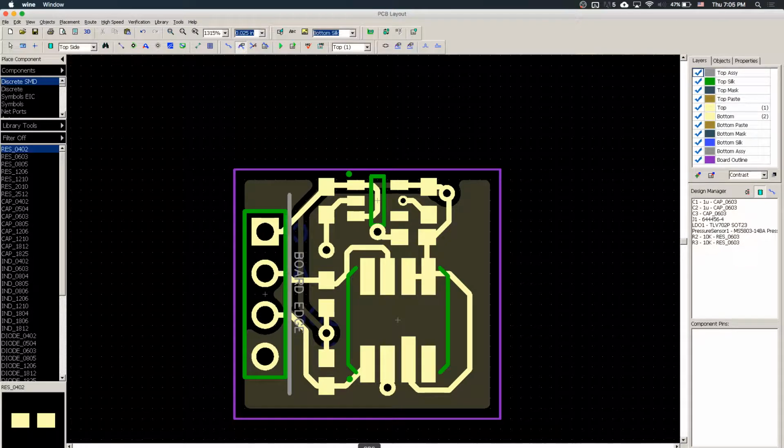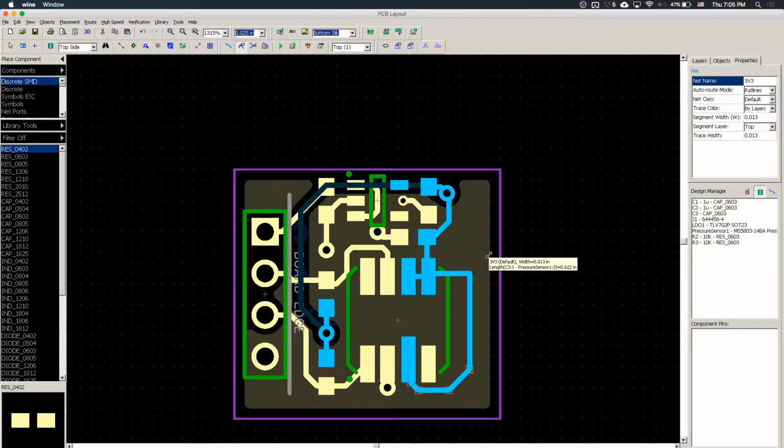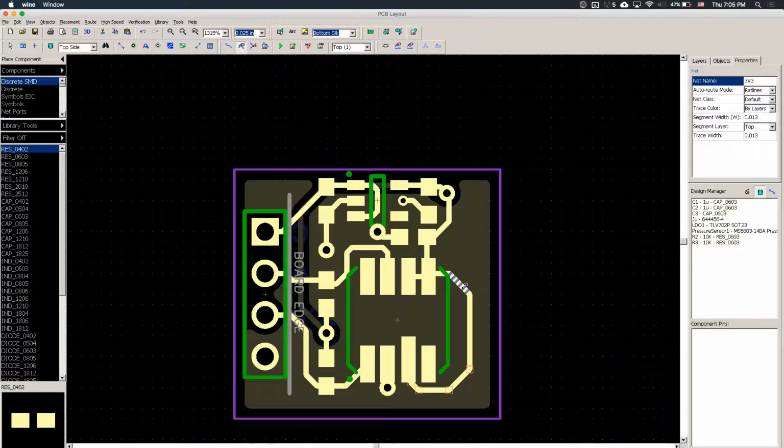So some of the design rules that you need to follow: do not use a 90-degree angle bend. For example, this trace, you could do that, but try to use 40 to 45-degree angles to make the signal flow through better. Place a bypass capacitor as close as possible to the component that it goes to, to reduce the noise induced to the pin.